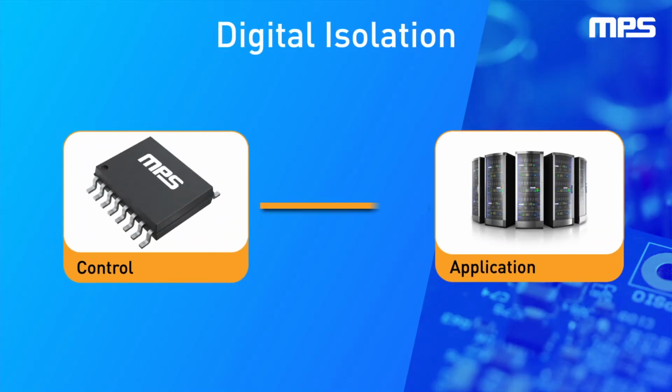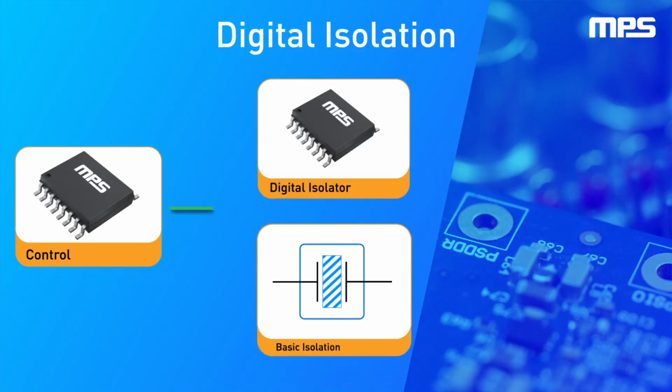Digital isolation is crucial for ensuring the safety of electronic systems, as it protects sensitive microcontroller units from potentially damaging high-voltage signals, noise, or other hazards, and allows digital signals to pass through. Basic isolation provides sufficient insulation material to protect a person or device from electrical harm. However, the risk of electrical malfunctions is still present if the isolation barrier is broken.